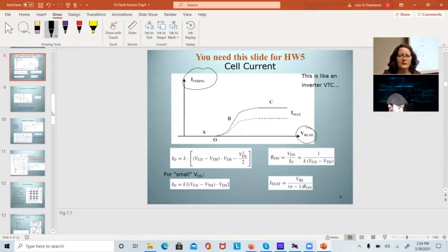When the current is 0, we're expecting this device to be in cutoff. When the current is large and stable with voltage, we're expecting this to be in saturation. No, not in saturation. This is triode. I do this all the time. This is triode. And B, the slopey region where we could get analog operation, is saturation.